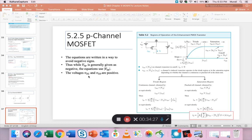Also, instead of dealing with VGS and VDS, we just use VSG and VSD, which is the opposite of how it is normally used in equations. But by using SG, we can just use the positive, right, instead of negative. So basically VSG and VSD are used rather than VGS and VDS, and then we stay with the positive. So you'll appreciate all this as we do some problems, but that is a point that I thought I should mention to you as we solve problems.